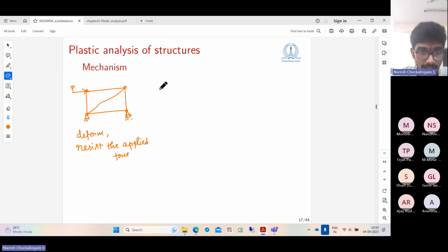On the other hand, if you cut down the middle bar, and you apply some force like this, it will just collapse. This is a 4-bar mechanism. So all these are free to rotate. There is no resistance at all. You can see that the members will not deform. Members will not develop any stress. It will just rotate rigidly and translate rigidly and form a mechanism.